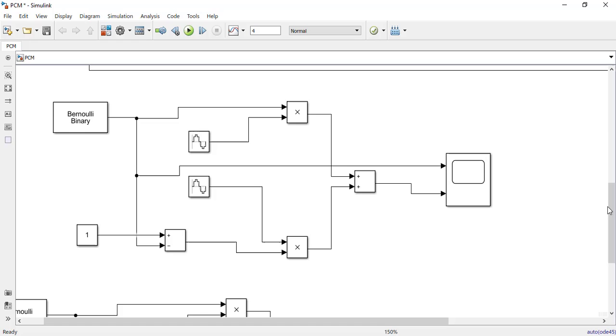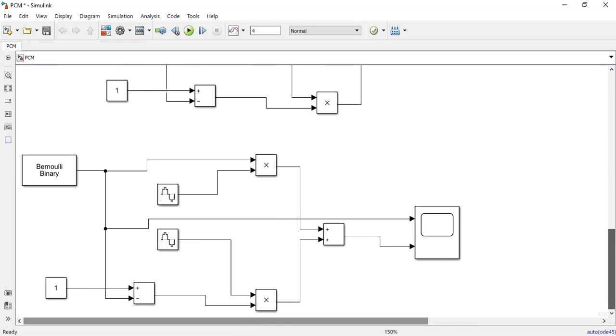So again, I have already developed a circuit for phase shifting. The idea is very similar, but now we will use the sine waves for different phases. When we were doing amplitude shifting, we were basically developing the same circuit. In that case, the amplitude of two sine sources were different. For the frequency shifting part, we were also using the same circuit, but now for two sine waves, the frequencies were different. Likewise, for the circuit of phase shifting, we will again use two different sine waves for two paths, and the frequency and amplitude of both the sine waves will be the same. Only the difference will be in phase.